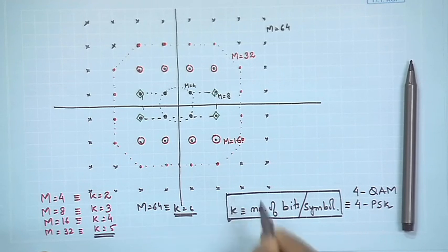So, in this fashion, if your communication system is dynamically changing the number of bits per symbol, which we will see at a particular time, you could use a scalable constellation, or you could use a flexible constellation, by virtue of which your transmitter receiver architecture could remain as simple as possible.